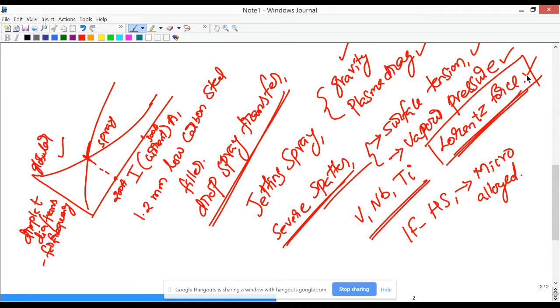So we'll continue with the assignment. We looked at assignment 1, question 2, and we'll move on to question 3. Compared to silicon, aluminum is a very strong oxide former, but unfortunately, it is a very poor solid solution strengthener. So the strength increase by adding aluminum is not that effective compared to the addition of silicon.